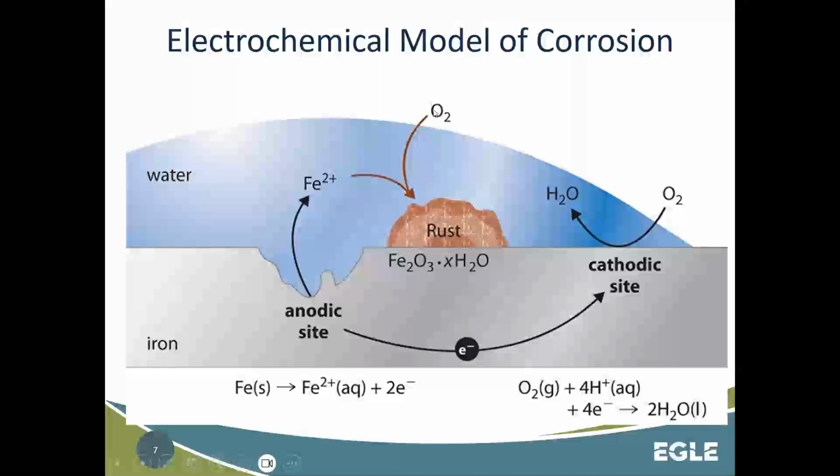It's combining, in this case, with oxygen that is just naturally occurring in the water and is forming rust. And this is what we call tuberculation, like we talked about on that second or third slide in. So you're having that rust, and it's falling out of concentration, precipitating out of the water and depositing itself on this iron wall in the form of ferric iron.